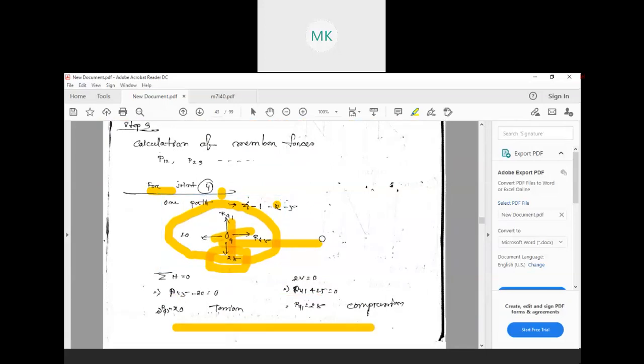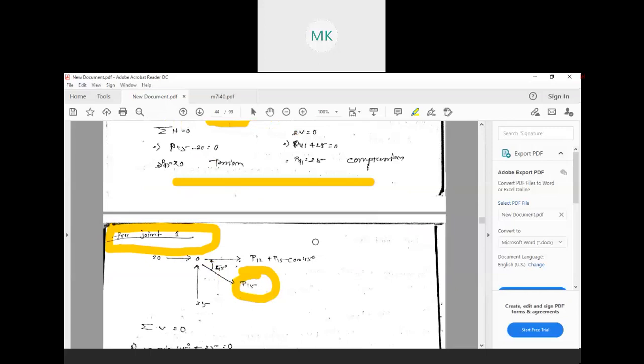In our case there are two knowns and two unknowns. Just put in the known values and, using the equilibrium equations, find the unknown values. In that way, you need to consider all the joints. There are 6 joints, so you need to do this for all the joints and all the members.